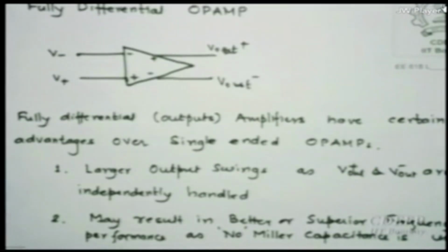It may also have a better frequency response or bandwidth, simply because there are no Miller poles here. In the normal stage you put CC, you got stability but you lost frequency bandwidth. There is no Miller pole or Miller feedback here, and therefore it will have a larger bandwidth. So in sum, maybe before we quit, one last slide on this same thing.